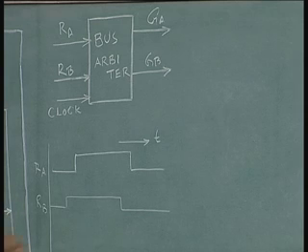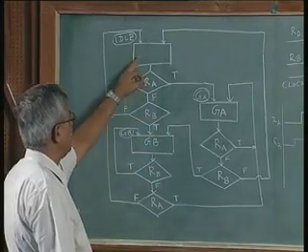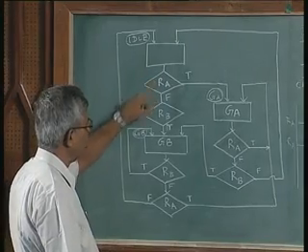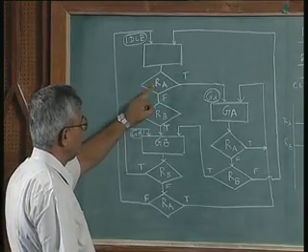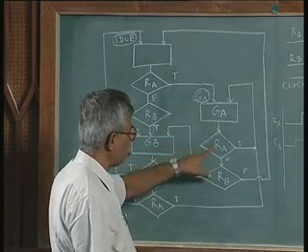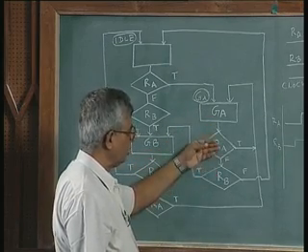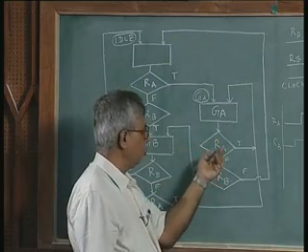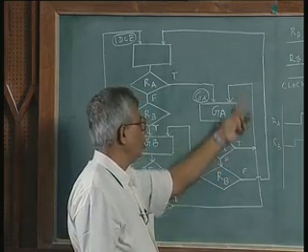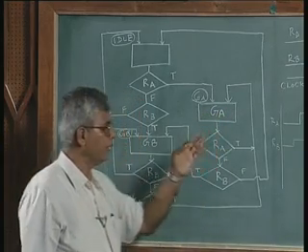With this we do the ASM, this was drawn in the last lecture, just for review, we have already drawn it. We have a state called idle state where both RA and RB are monitored. If RA is true, naturally it gets a preference and GA is generated, and GA continues to be generated as long as RA is true. Only when RA is false, it goes and looks at B. It means as long as RA is true, it goes through several clock cycles during which GA continues to be generated.